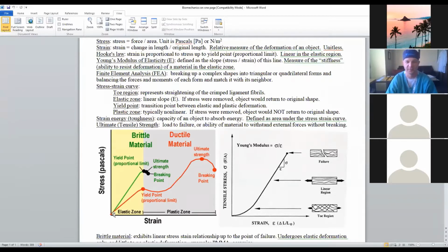They've never asked this before, but this red line here is for a ductile material. What if you stop right here and let it go? Can you see my cursor? Yep. Okay. If you get to this point on the curve and then let it go, it just follows that exact same curve back down and doesn't have any residual strain or residual set. What happens if you take it past the yield point and it begins to plastically deform? Let's say you get to here and you release the stress you've applied to it. How does that behave?